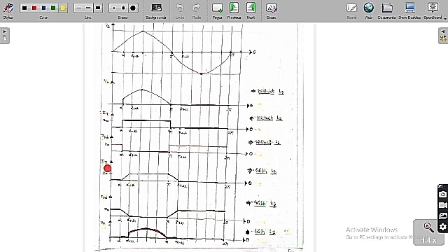So now let us take the thyristor current, I T. Up to alpha it is 0. After that it is going to slowly increase. Let me assume some alpha plus mu, so it is going to slowly increase up to alpha plus mu. Again up to pi it will be the same, I naught. Again it cannot suddenly become 0, so it is going to slowly decrease from pi up to pi plus mu. So a small increase from alpha to alpha plus mu, and a small decrease from pi to pi plus mu.